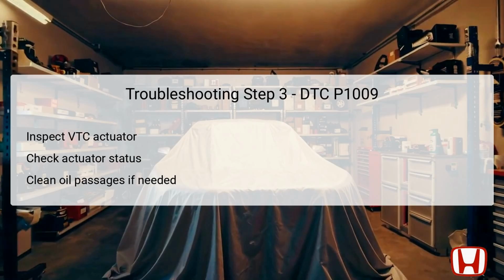The third step in diagnosing DTC P1009 involves inspecting the VTC actuator A itself. After determining that the VTC oil control solenoid valve A is functioning correctly, carefully examine the actuator for any visible signs of damage, wear, or malfunction. Inspecting involves checking for any oil leaks, physical damage, or blockages that might prevent the actuator from operating correctly.